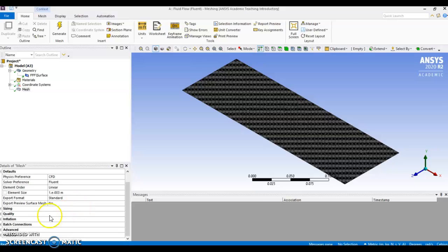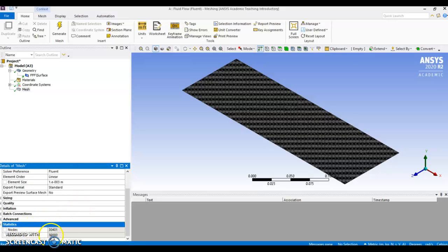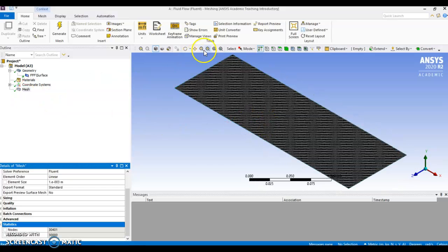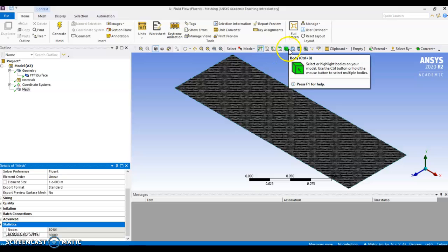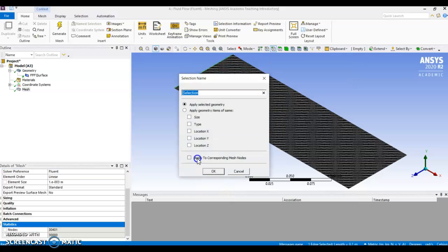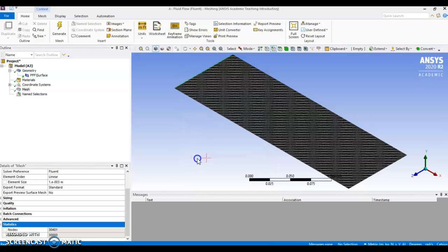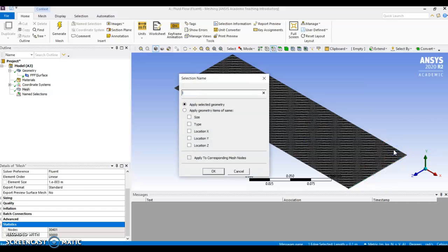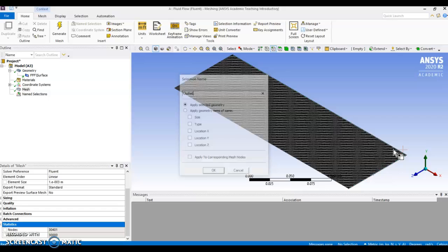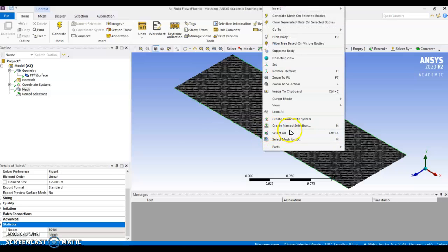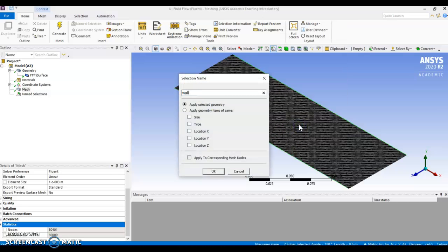And so here's our mesh. Let's go inside down. You can see we've got 30,000 elements. It's fine. It's quite dense to me anyway. So we're going to use these features at the top. Select the edge. Create our name selections. So you can right click, create name selection, inlet, and then we're gonna go here, right click, name selection, outlet, and then we're going to click on this, press Control on your keyboard, and then select this edge, right click, create name selection, wall.